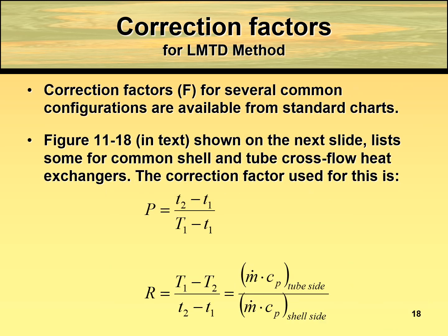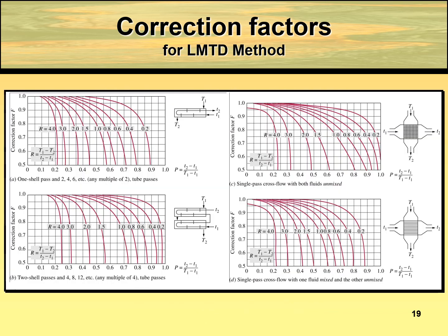So the correction factor may be used with several common configurations which are available in the standard charts in your textbook, given by P and R. So what is P and R? They are given by these temperature ratios.